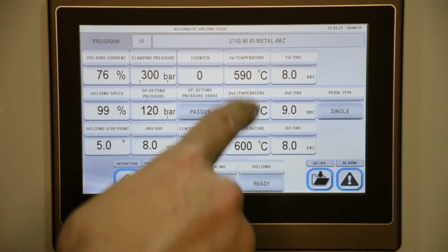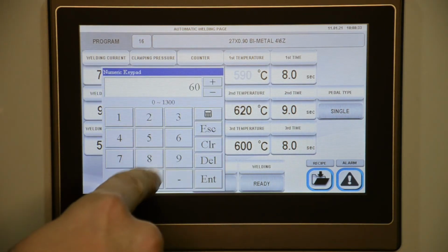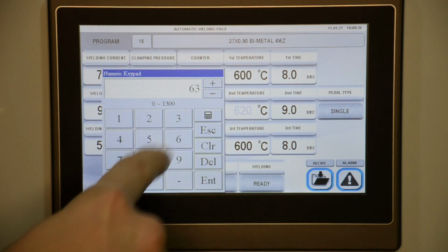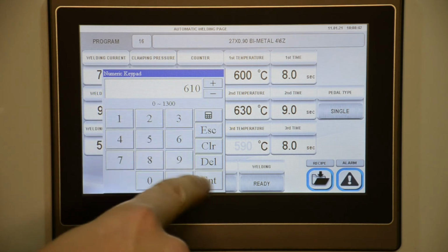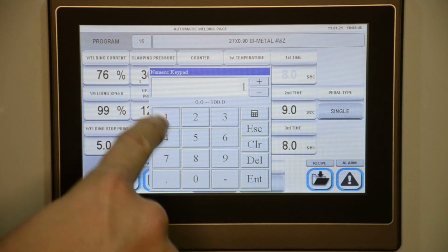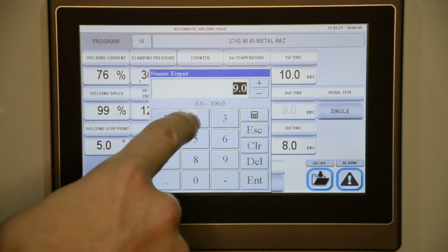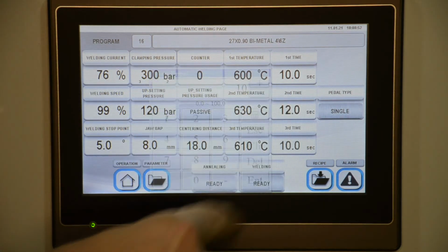Temelsan flash butt welding machines have a special annealing process. The machine uses 3 different temperature sets and 3 different time sets for each temperature value. Annealing temperatures are dependent on the blade characteristic and mixture of base material. After operation, in case your blade breaks tear like a plastic, you should decrease the second temperature set value. In case your blade breaks like a glass, then you have to increase your second temperature set value.